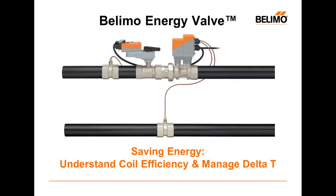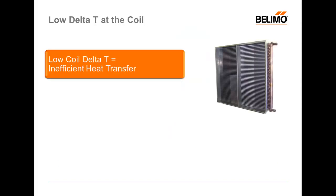And in order to understand that, we're going to talk a little bit about coil efficiency and how managing Delta T will save energy. Let's first talk a little bit about Delta T. Delta T at the coil refers to the difference between the supply and return water temperature from your coil.